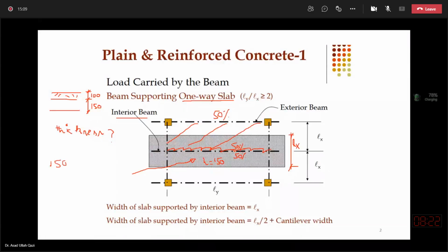For example, for reinforced concrete we will use a density of 2400 kg per meter cube. And for PCC or, I would say, floor finish, a good selection is that we might consider a density around 2300 kg per meter cube.